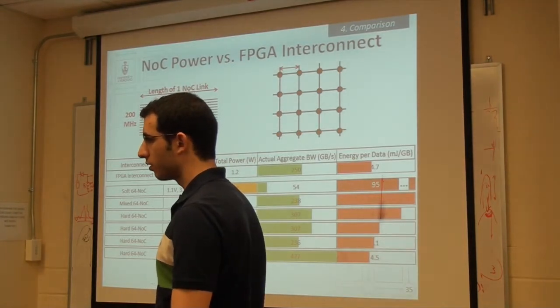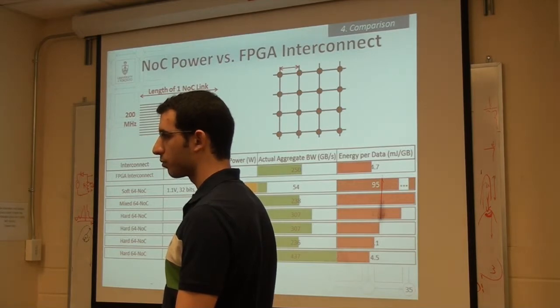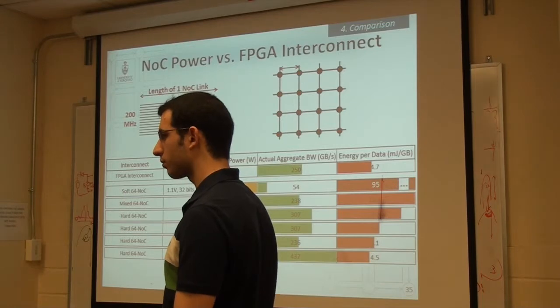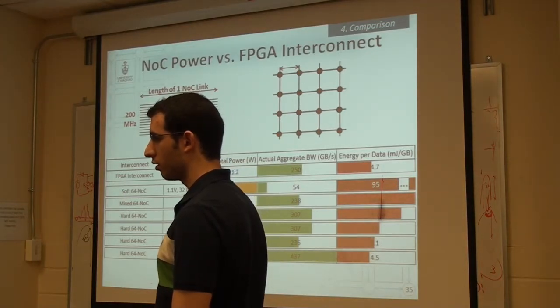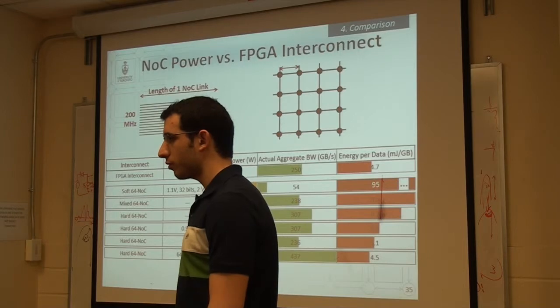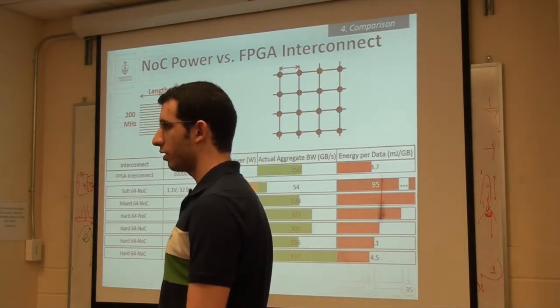But also, what about the unpredictable effective latency when you have congestion? Because you're no longer sharing links now between multiple virtual connections. You don't have dedicated links as in an FPGA. What do you think, how does all this play into simulation? So not for correctness, it's going to work, but what about testing for performance? How do designers work with this? So that's a very good question.